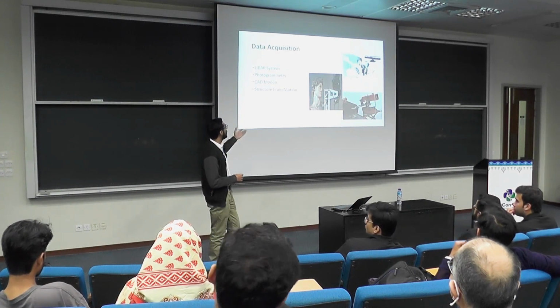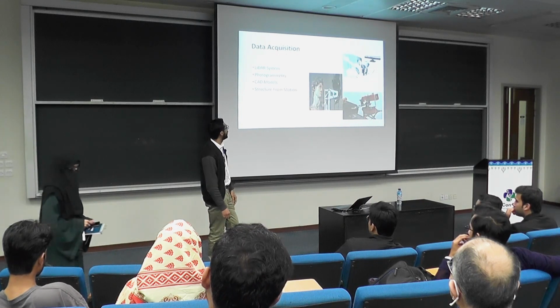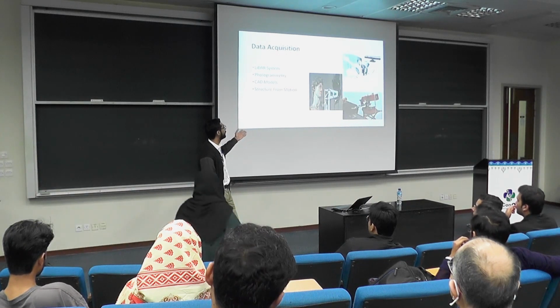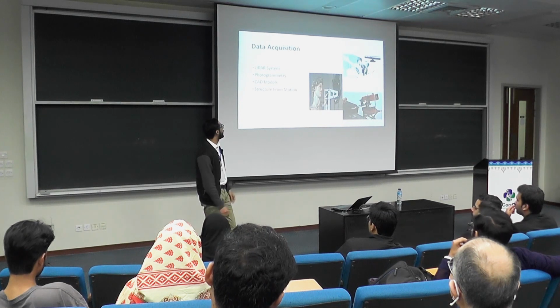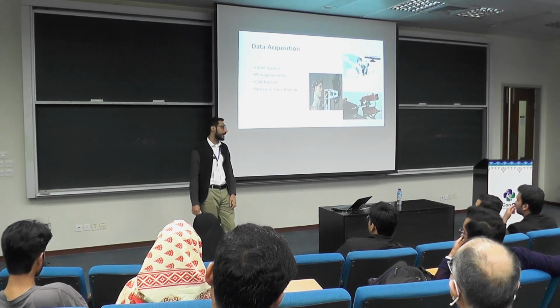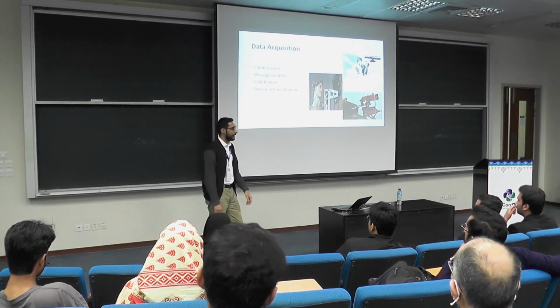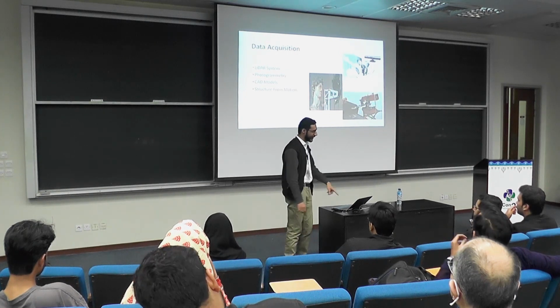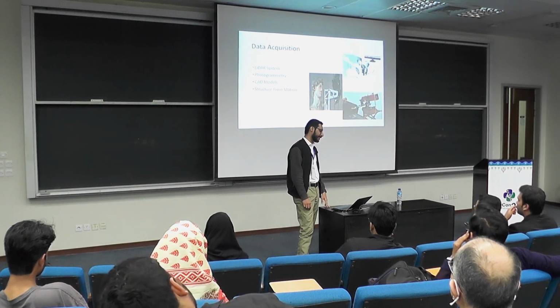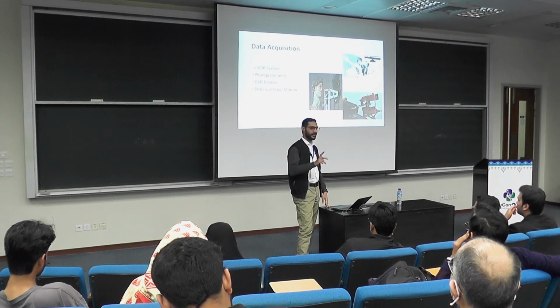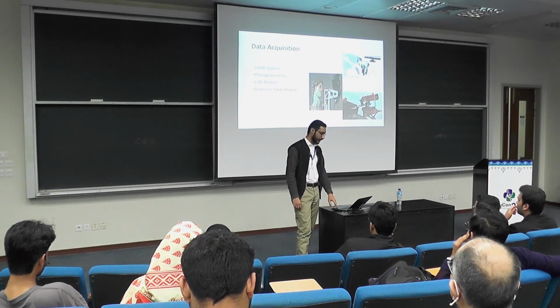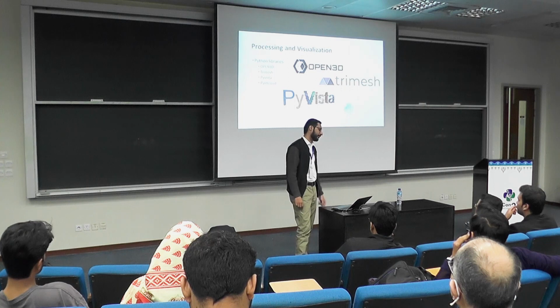Some of the techniques or equipment I mentioned are the LiDAR system that uses light sensors, photogrammetry, CAD model, structure from motion. I would suggest everyone to use a LiDAR system if they are working with point clouds, because photogrammetry can introduce a lot of noise, which can be a real headache.